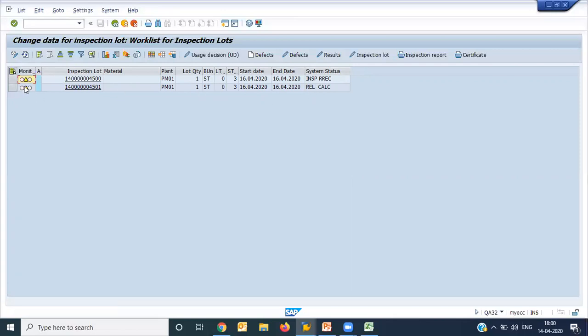It means now you can use this inspection lot. So as an end user, I have performed the pressure gauge calibration live. I have put 0% load and I have checked what the value is. I have put 5 kg load. I have put 10 kg load in this way. So whatever your observations were, you have to enter them here.